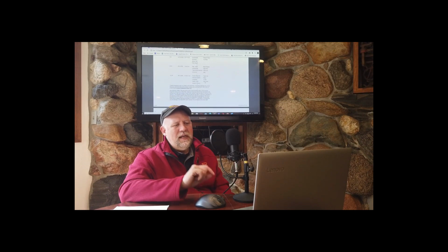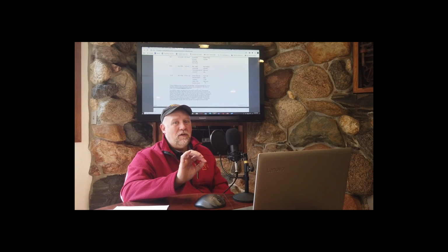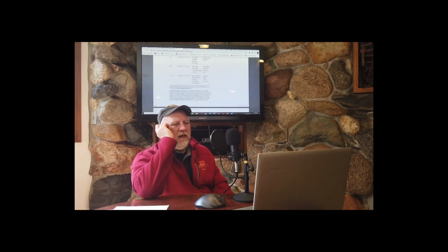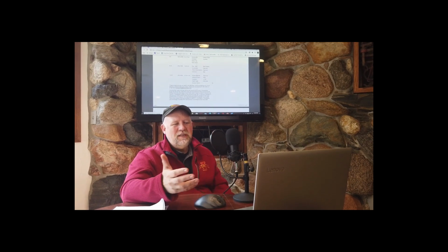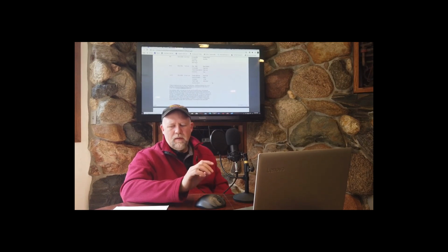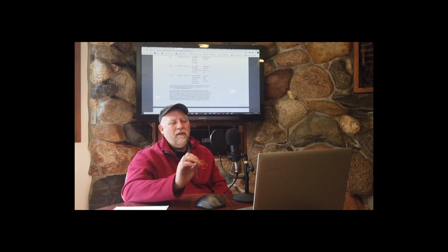MERV rating of 13 to 16. That's where we get more and more efficient, and also more expensive and larger. When you're getting into MERV ratings of those, that's like high-end commercial applications. You'll also see it for surgery, hospitals, healthcare, communications applications. Those are probably the top ones that you're going to see most of the time. And then beyond that, there's actually even better filters. They are called a HEPA filter, high efficiency particulate air filter. And I've got examples here of each.